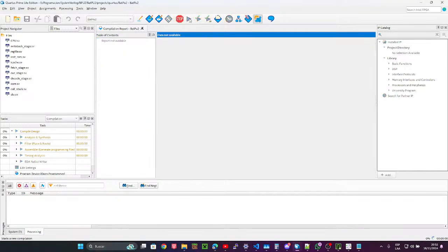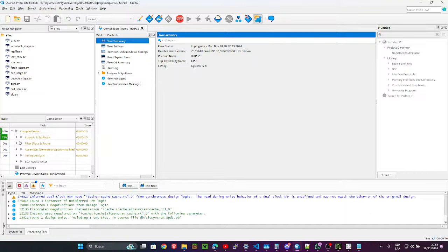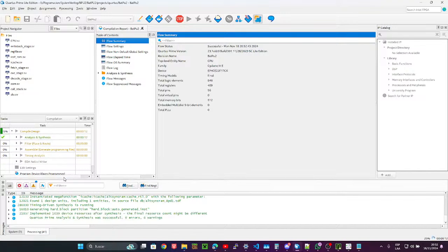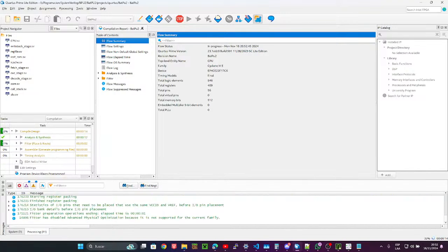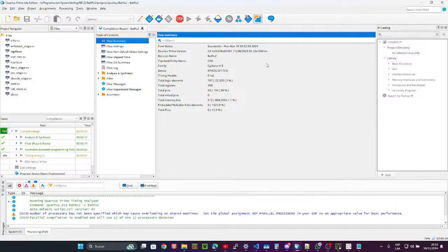Oh. And that's changing those two coefficients, like the divide coefficient and the multiply. So if you put the divider in the feedback, it actually multiplies the output of the PLL by that amount, because they have to be the same frequency on the input. And then you divide on the output, you get essentially a fractional multiplication on the input frequency. You can get quite a lot of range from that.